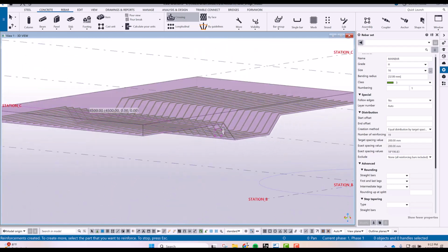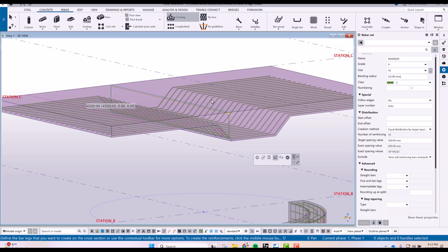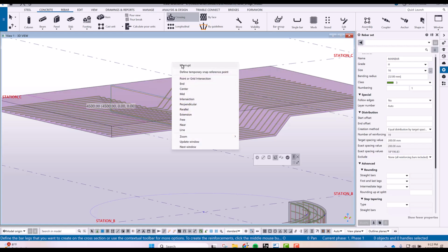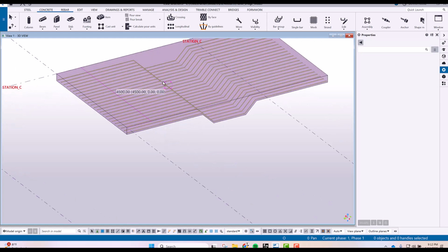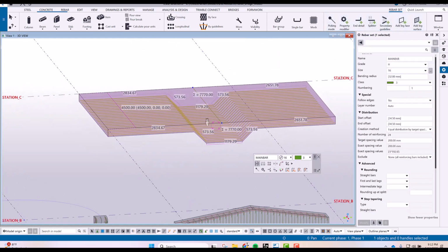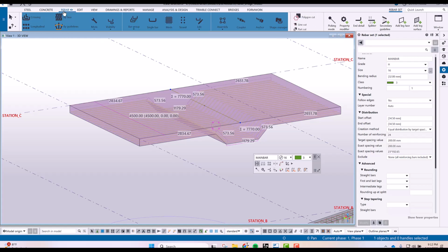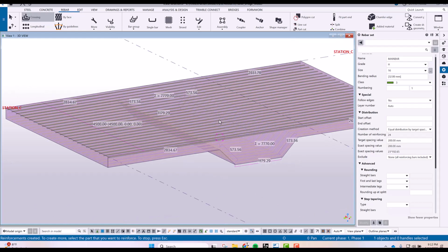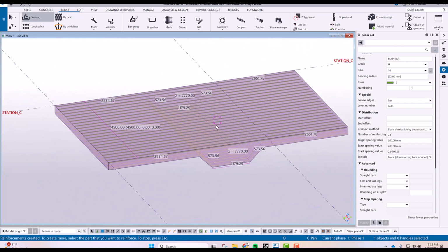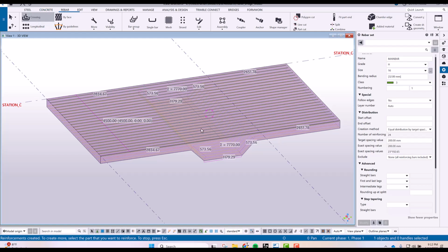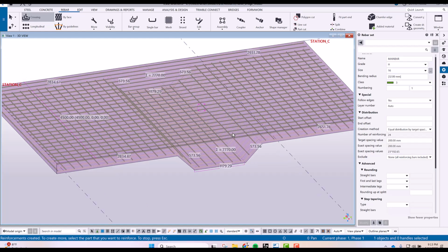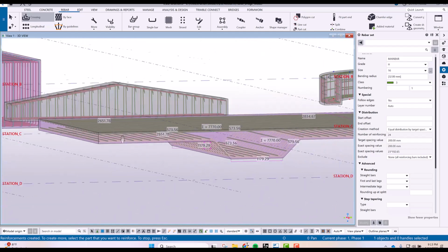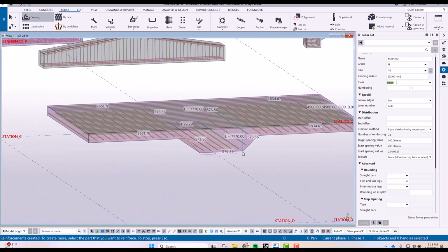it will give you this shape of the rebar set. Okay, so there you go. Now if I'm going to add the crossing on the top, so select the top, it's like a longitudinal bar, okay? But if I put the crossing also on this side, and then click this bottom, you can see here, it will place according to the shape of the concrete.